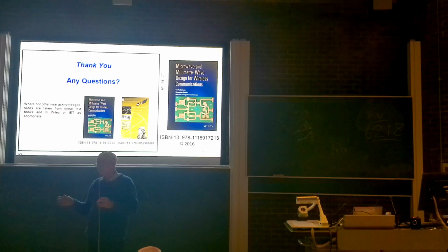A better name for it, which they won't use, which I try and promote, is long drain, because the drain inside the transistor is a much longer length, and it enables you to operate at the same current but a much higher voltage. So it's a very clever technique. But basically, we are at the limits now. We really are. The physics is the limit.